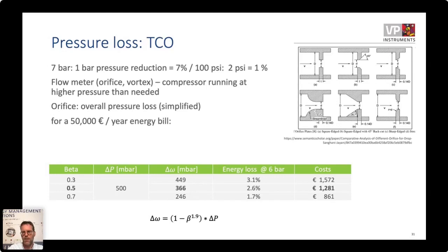especially when using flow meters for compressed air and at the supply side where you still need that high pressure. Then you need to be very careful with selecting technology that has a very low or even virtually no pressure loss. And that's why insertable probes are such an excellent choice for this application. And of course, you could say ultrasound is even better in that case because you don't have any pressure loss. But that comes at a price.